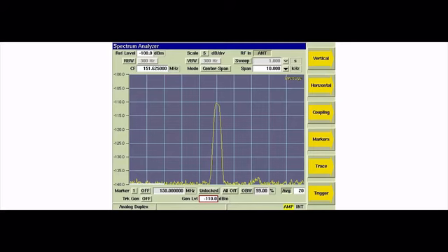In standard configuration, the spectrum analyzer frequency range is usable from 100 kHz extending to 1.05 GHz. With option 58 installed, the frequency range is extended to 2.7 GHz. The displayed average noise level is -125 dBm, typical with 300 Hz resolution bandwidth, antenna port terminated, and a 20 dB sweep average. When the preamp is turned on, the 3920 has a typical noise figure of -9 dB, leading to a spectrum analyzer noise floor of approximately -140 dBm with a 300 Hz resolution bandwidth filter selected. This ends the brief overview of the 3920 spectrum analyzer.